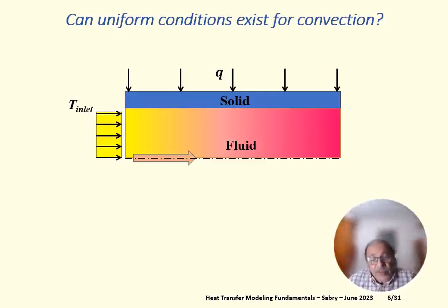which will cause a heat flux through the walls. And this heat flux will influence the net flux arriving to the fluid. Even if the flux outside the solid wall was completely uniform, the flux at the interface between solid and fluid will not be uniform. In fact, having a uniform heat flux is very difficult. Having uniform temperature is also very difficult, as I have explained before. But this is not the whole story.